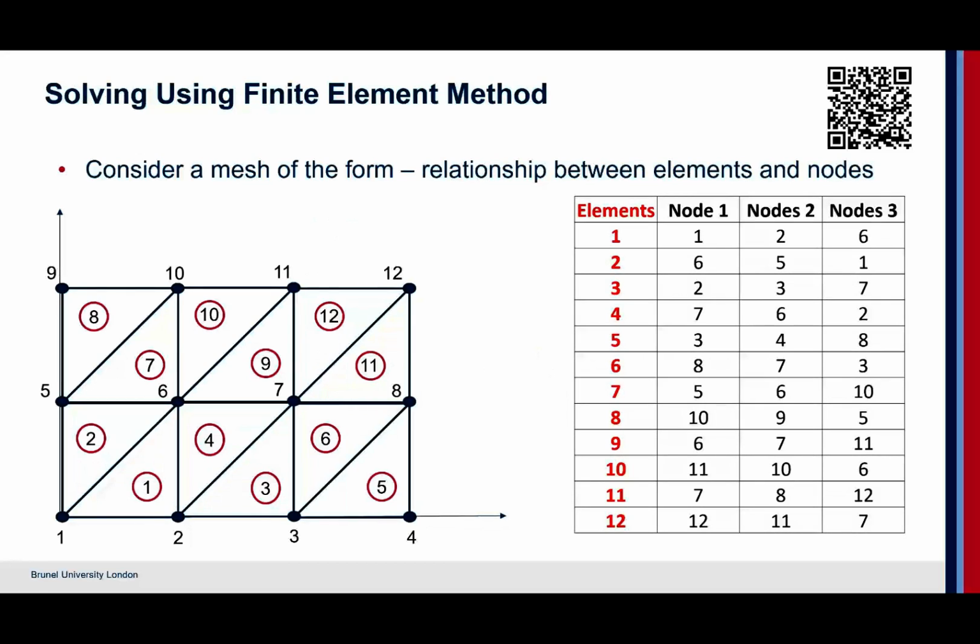Now, what becomes more complicated is the node numbering. So when we were in lecture 3, I think, there was a question about the link between local and global numbering. Now, essentially, what we have is the element number on the left-hand side and then the corresponding nodes. And what you have to do is keep track of, for a given element, which nodes correspond to that. The other thing you have to notice is each of these nodes is now shared by lots and lots of different elements. So within our matrix, this means that a given node will actually be contributed to by the deformation and change of each of these wider range of elements.